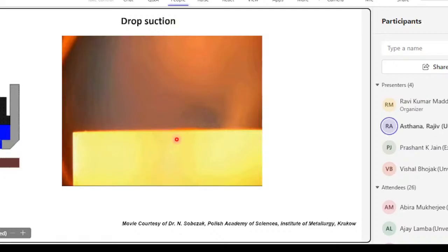In some systems, we see that even though wetting is poor, which means the contact angle may not be very low, there is still adhesion or bonding. So this little ceramic substrate was picked up by this solid, even though the angle of contact was not very high between the two. Many alloys show high adhesion to substrates in spite of weak spreading of the liquid.